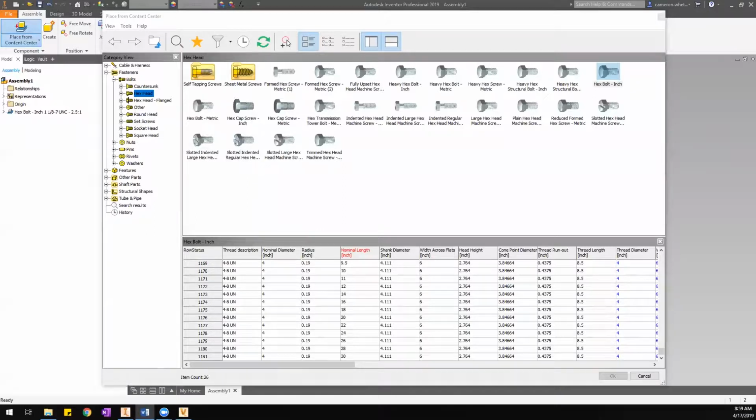If you chose not to install them but now you want them, you run the Inventor installer again. It wouldn't reinstall Inventor; it would know you already have it installed, but you could choose to add and remove features, add in the Content Center files, and it'll install those for you. If you don't have the Content Center libraries installed, that's how you do it.